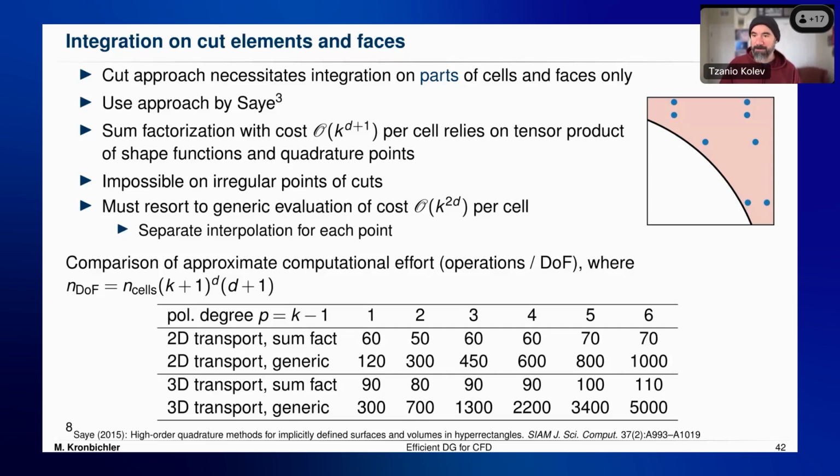We do some work on simplices right now in one of our projects, so I think I have some insight into them. What we typically observe is that, when you compare them on a degree-of-freedom basis, simplices are between a factor of 3 to 5 slower per unknown than the hexahedral element shapes, approximately. It depends a bit on which algorithm you choose, but if you use low-order simplex methods, up to degree 3 maybe, then you would typically choose the full interpolation matrices for a matrix-free algorithm, so you don't use any structure.